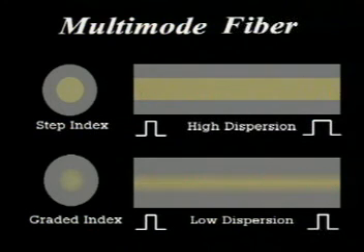In a graded index fiber, layers of glass with smoothly varying refractive indices comprise the core. Because the core center has the highest refractive index, the axial mode is slowed down, while higher-order modes travel faster, so all modes will arrive at the end of the fiber closer together. This reduces modal dispersion, allowing long-distance fiber runs or higher transmission speeds.